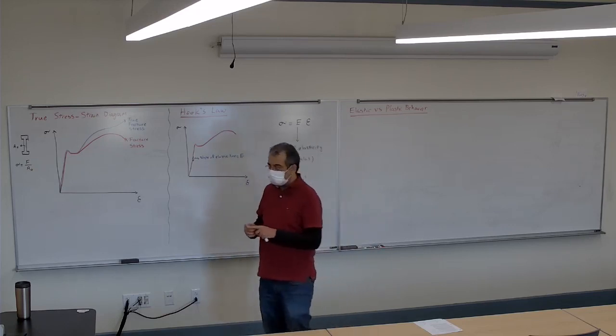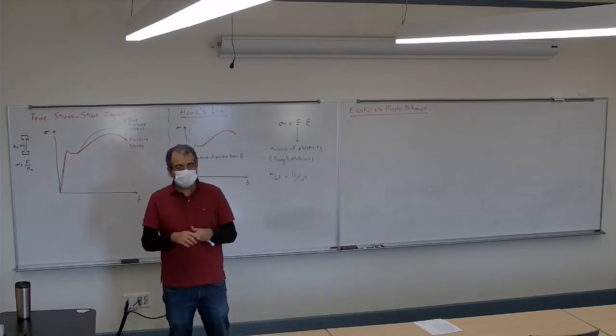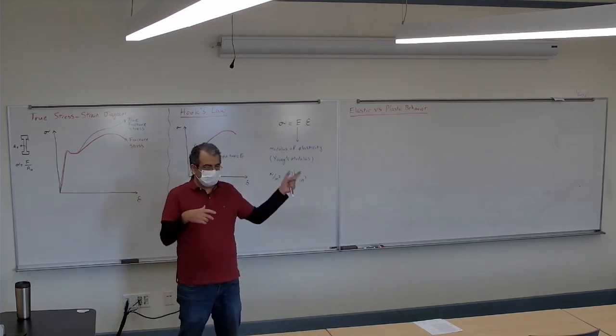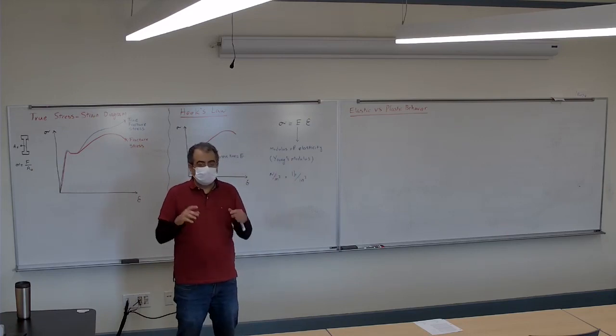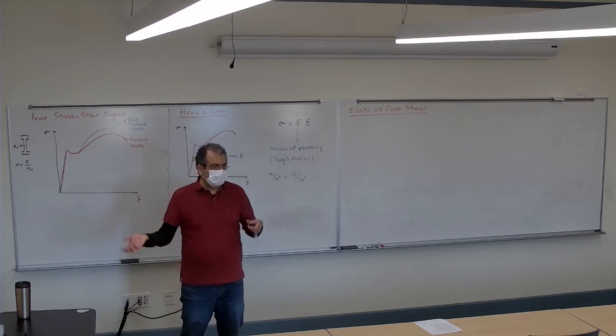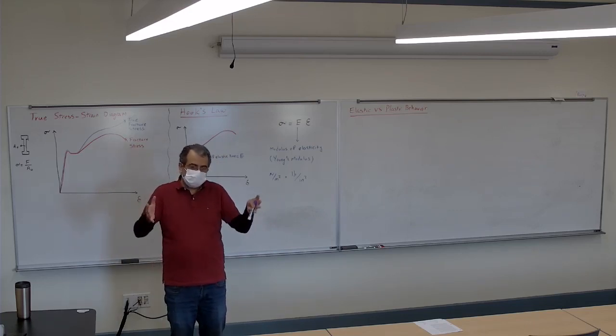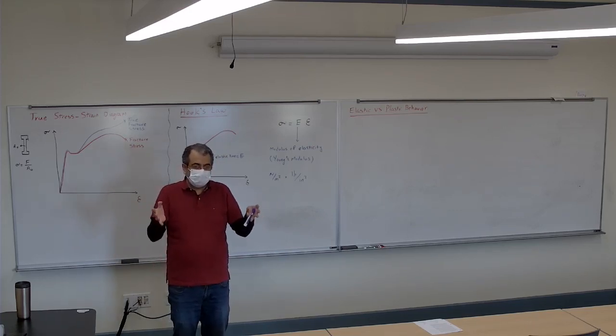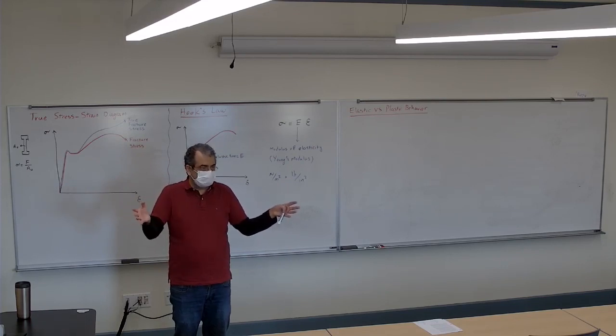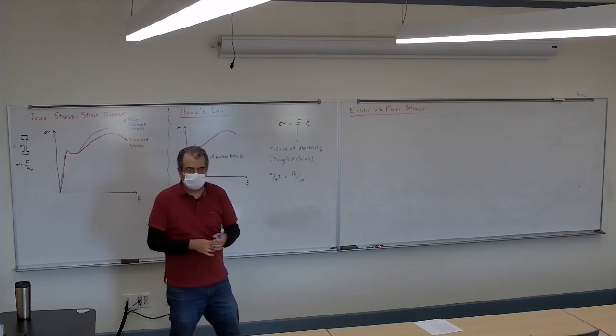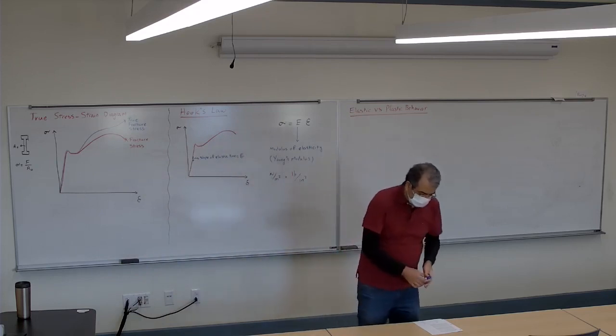So it's for bending or just tension. As I said, we assume the concrete doesn't do anything in tension, so we add the bar. In compression, we assume the concrete takes care of it. But if for any reason it goes under tension, then the bar is going to take care of what's happening.